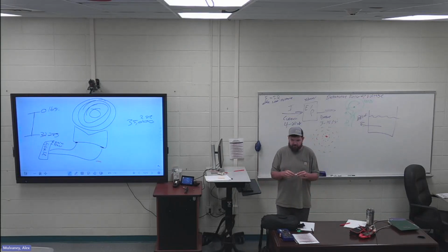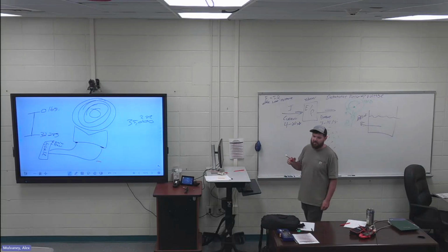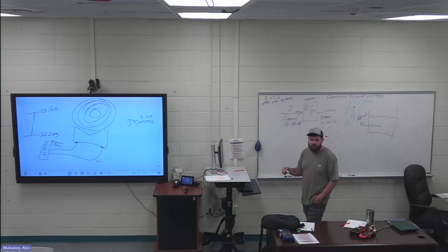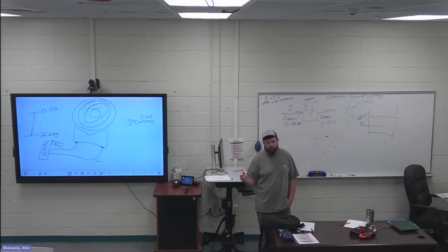Whenever you use the beeper pen that beeps whenever you have voltage, that's how this works. If I have a beeper pen and I get within that field, that pin can sense that, it starts beeping, the light turns on, right? The reason this is so important is because of induced voltages, right?